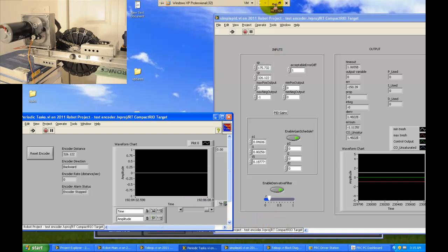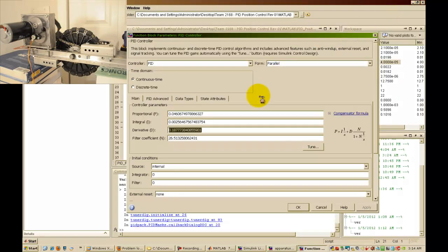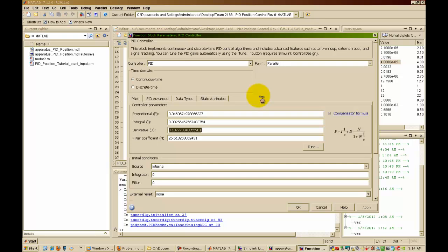the filter coefficients. Now, however, I ran the gains for a custom PID controller that I personally implemented. The controller I use has advanced features such as derivative filtering, integral windup prevention, as well as deadband removal. All of these advanced features make this controller respond better than a standard PID controller. I've made this controller available to the FRC community, and I encourage you to use it in your next robot. If you do, I'd be happy to hear about your successes or any failures that you ran into.